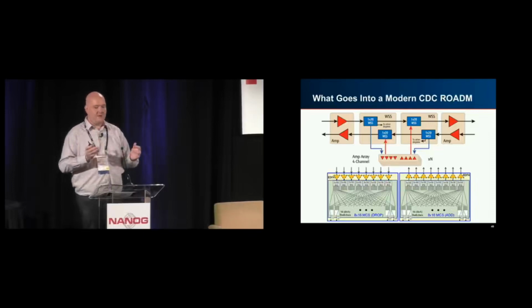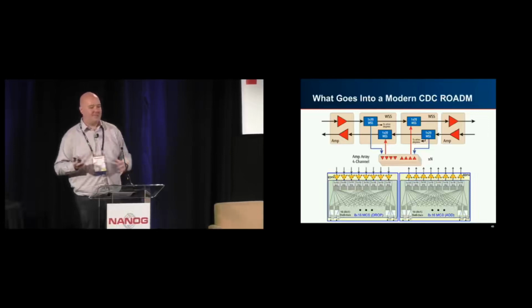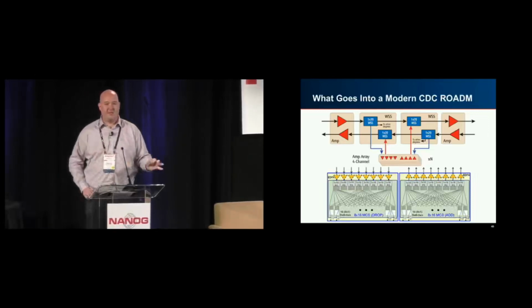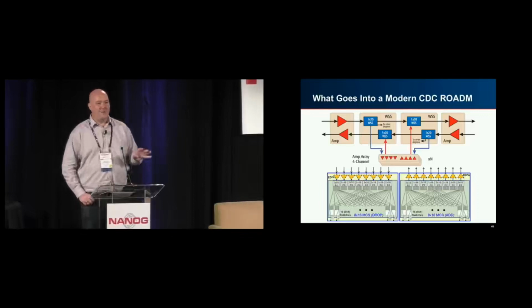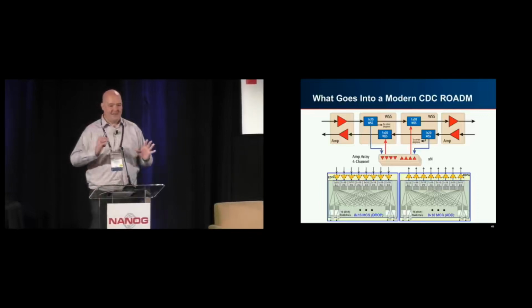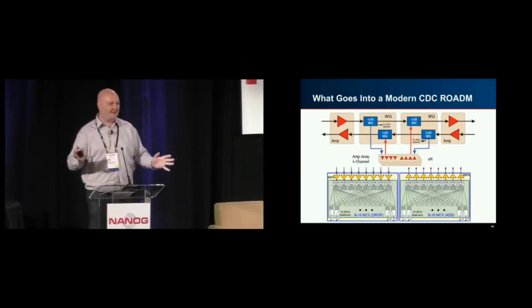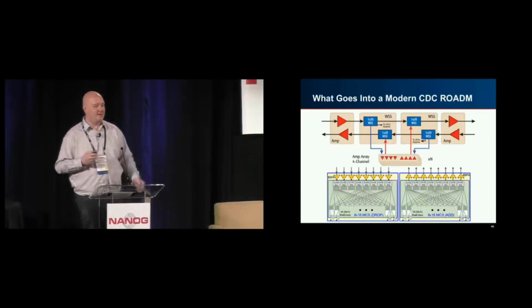And then it goes to what's called a multicast switch. A multicast switch is literally an array of 1x16 splitters. Here's an example of an 8x16 multicast switch. All that is 8 different 1x16 splitters. You take the light and split it into 16 different things, spreading the light out like crazy. Of course, you have to amp it again because it's now very dim. But at the end, you've replicated the signal to all of these different ports, so any one of them is capable of receiving the signal without having to be locked down to a specific thing. But you see there's a lot of complexity, a lot of loss, and a lot of amps that go into this system. So you pay for it too.